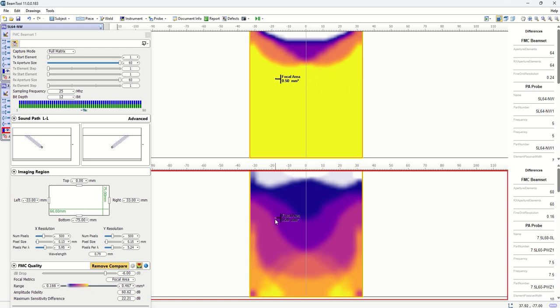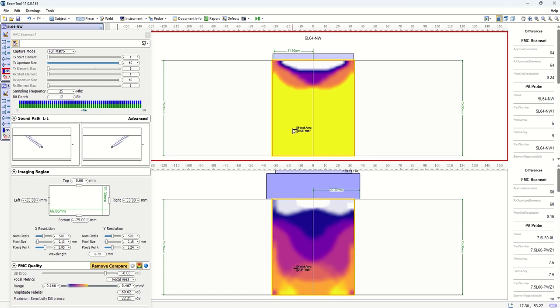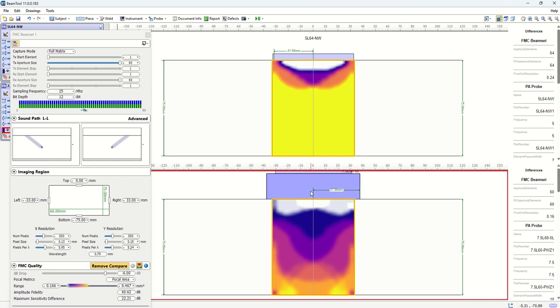So what this means is that with the new technique, we're creating a technique that is more focused, with better focus quality. With that logic, if the technique that had worse focusing or larger focal area could see HTHA damage at an early stage, then logically the new technique should also have at least the same level of sensitivity to see those.